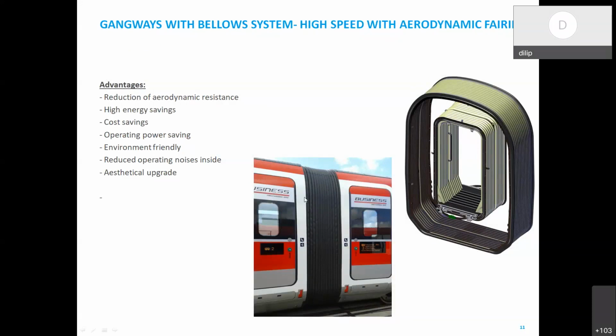The role of this exterior bellow is, let us suppose this bellow is not there, a lot of electrical couplers, electrical wires will be going here, which are accessible from the platform to the passengers, and they may try to tinker. That is one. And another thing is there is a recess here. When the train is running at higher speed, the aerodynamic forces, I mean drag, will be higher because air will be stagnated here